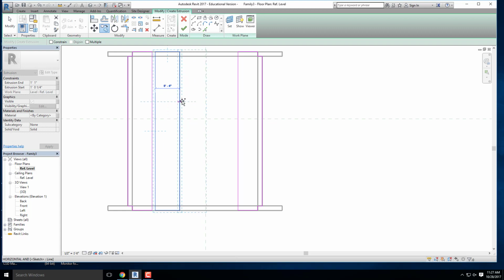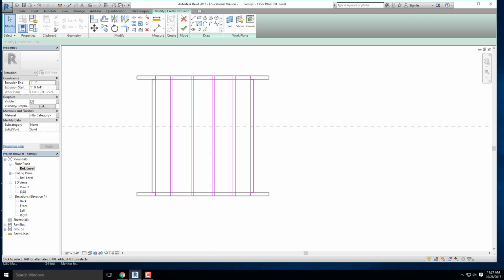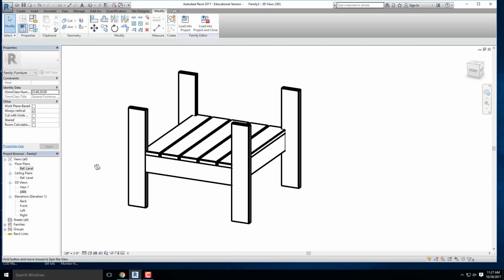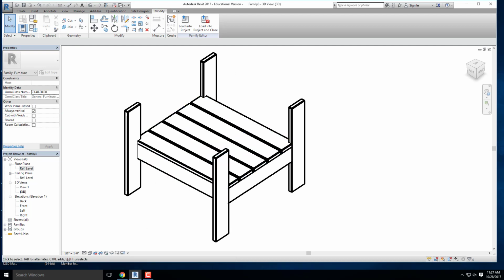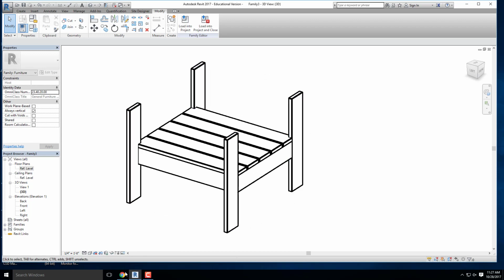I'm going to copy it over how much? If I want a 1/2 inch spacing between it? 4.5. So 4.5 inches, right. And then I'll do that one more time. Look at that. So we have all the exact same size boards. We have the exact same spacing between all of the boards. Okay? Hit the check mark. And now we have all of the base slats for our chair. All right, let's look at a couple of our other pieces.